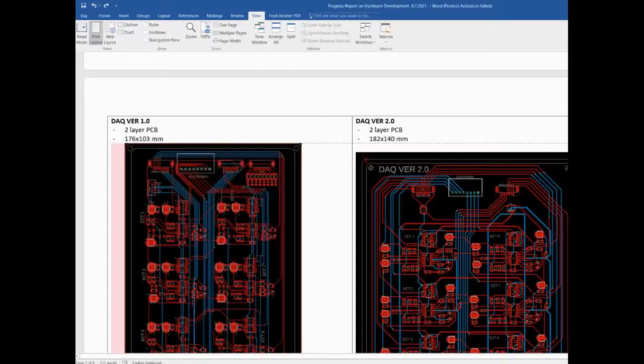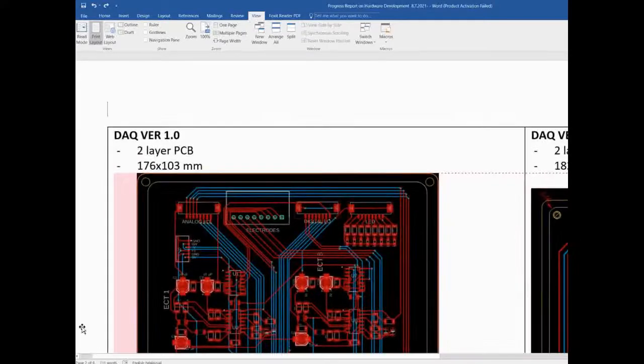So this is my switching IC. This is the digital circuit, and this is the analog circuit. So it's in the same area. This causes signal integrity problems, and also EMI problems. There are lots of causes of EMI problems, but one of them is the mixed analog and digital circuits.